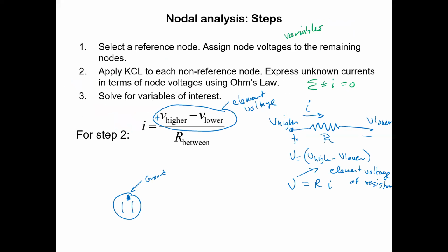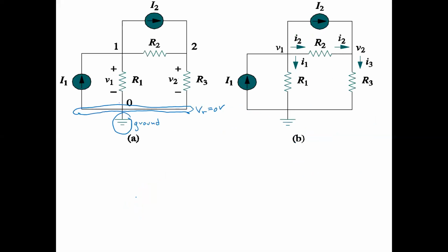If your house is wired correctly, that ground will come out of your house and go to a metal pipe, maybe your water mains, something that's actually going into the ground, attached with a big cable. That keeps the reference voltage of your house at a known value, so you can't build up potential. If you don't have that grounded, you can get potential buildup and then shocks. It can be dangerous, so it's a really important part of the wiring of your house to have a ground. And that's the same effective thing on the circuits we're working with in the lab.